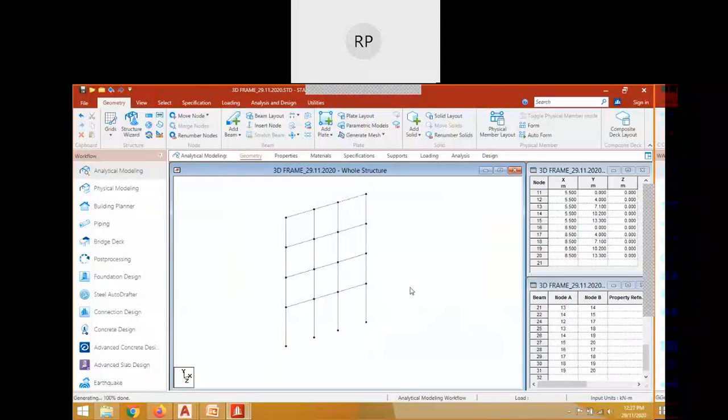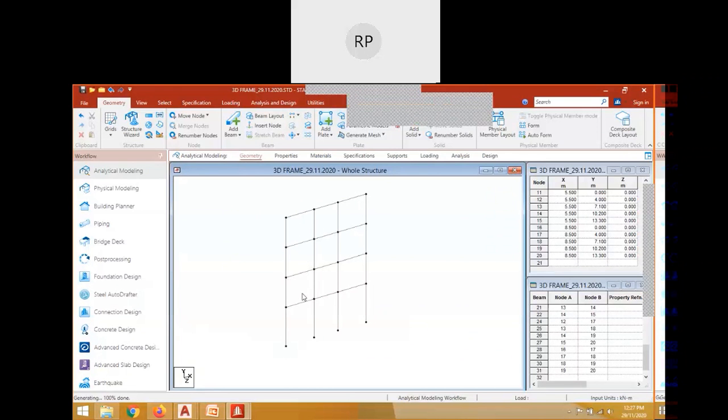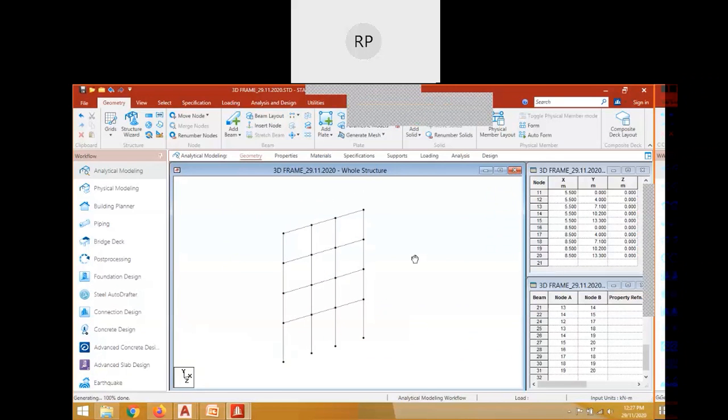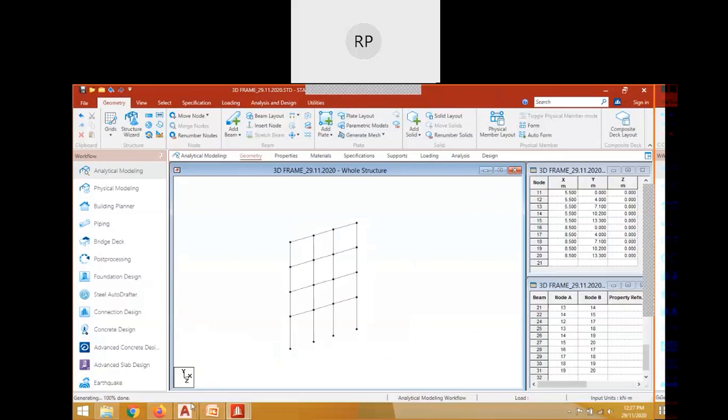Now see here, this is how your structure will look now, as a plane structure. It is not a space structure; three-dimensional is not there, only plane structure. Here, this is the fixity level, this is your plinth level, and this is your first slab level, and in between, this is your ground story, this is your first story and the third story, sorry, second story. So ground, first and second, a G+2 building, very simple, right? Now I have created the geometry in x direction.